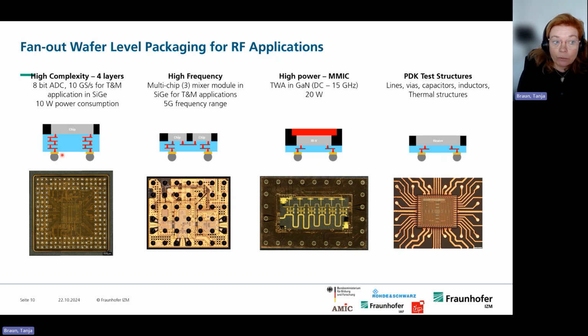Of course, it is multi-layer, and multi-layer in this case is not 2 or 3 layers. It might be even 4 layers or even more. I think you easily see the wish for more layers if you discuss with designers, especially here in the RF area. One challenge, of course, is warpage. If you stack one layer on top of the other layer only on one side, you can imagine that you have to somehow deal with warpage in this case. Multiple die integration, of course, we have seen before. This is one example where we had one package with 3 dies included and 2-layer routings.